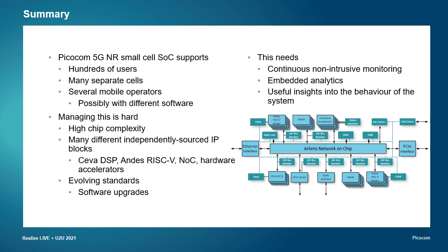So a lot of traditional methods of analysing what's going on, for example using watchdog timers, really only apply to the software element of the system. Using embedded analytics like this, we have something that we can apply to both hardware and software at the same time.